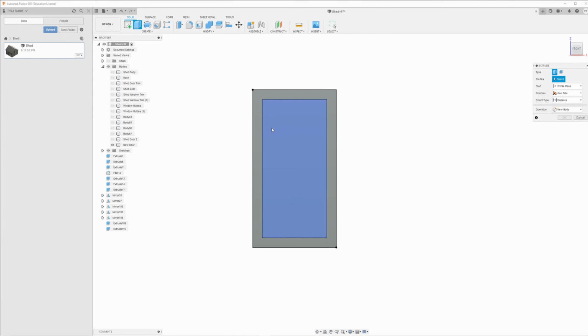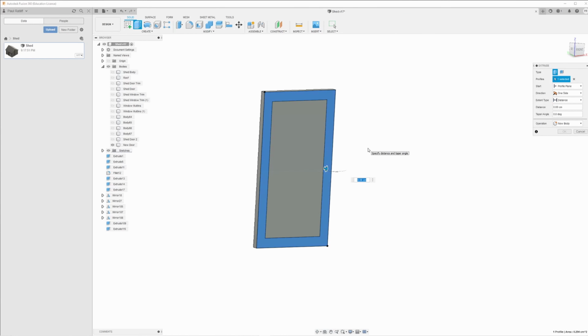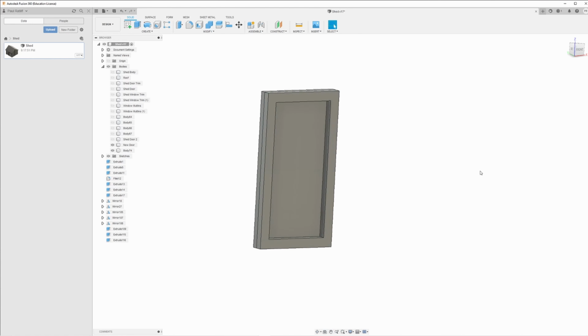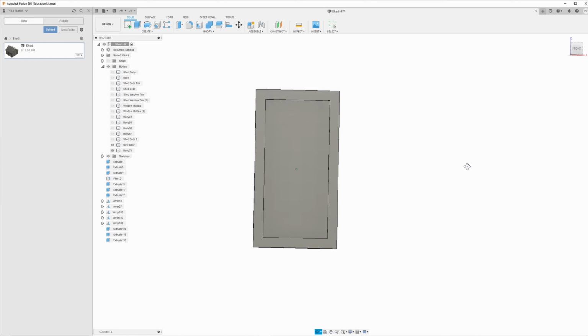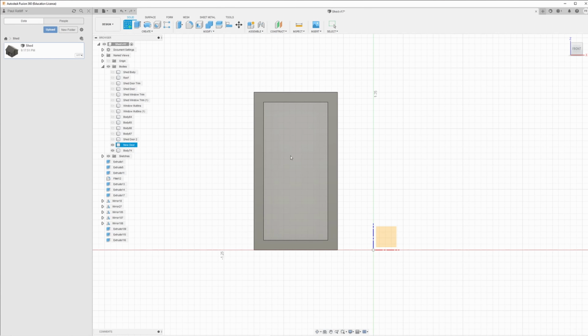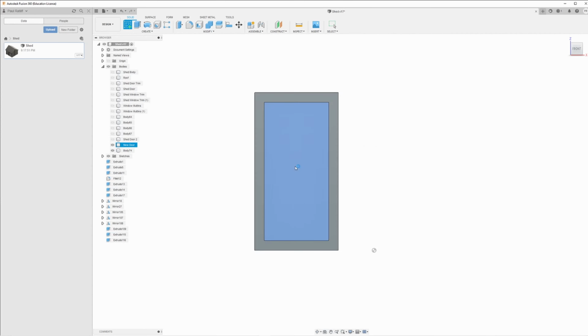Now let's extrude this out. I'm going to extrude it out, I think, 0.06 of a millimeter. And as always, a new body. That looks good. Now, even though this door does not sit on the origin itself, over there's the origin point, we can still use this door and find the center point, which is pretty cool for the next part here. Create another sketch, create it on the door itself, not on the ridge or rim or outline of the door, but on the door itself.